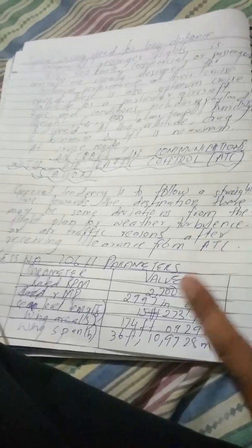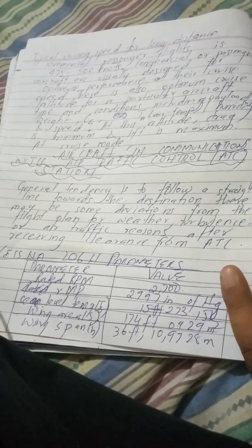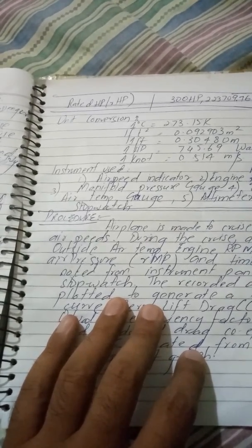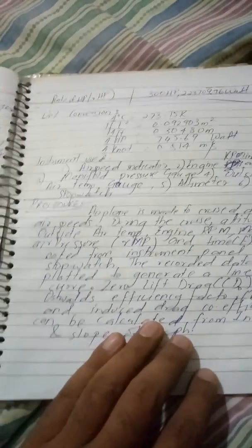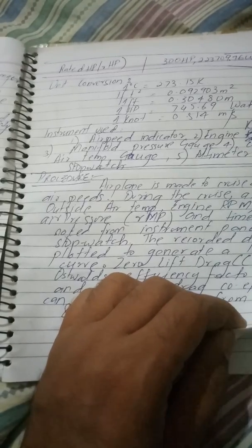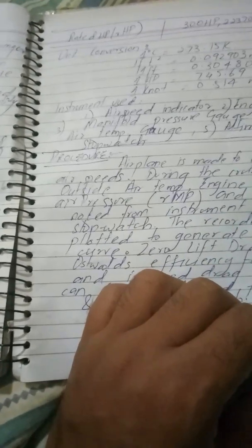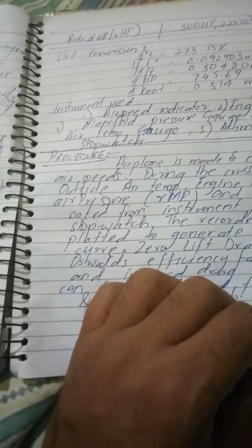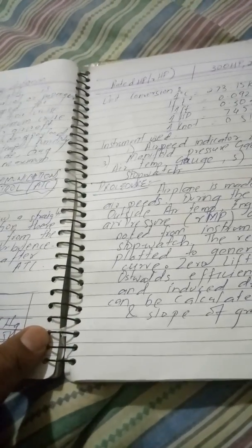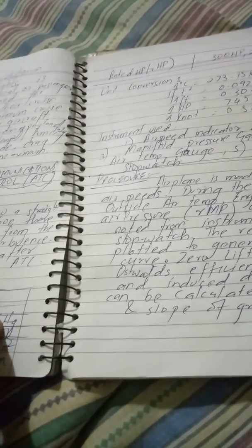With the different parameters given, such as RPM, manifold pressure, sea level temperature, wing area, wingspan, and rated horsepower, we can convert them into standard form, use them against the instrument, and calculate under standard conditions. Then we record and plot it to see the slope or intercept, to get the lift and drag coefficients and complete the equations, and we can see the different results for different parameters. So this is a short video, not directly linked to the airspeed indicator, but obviously the instruments are used, and that is why I have used it.